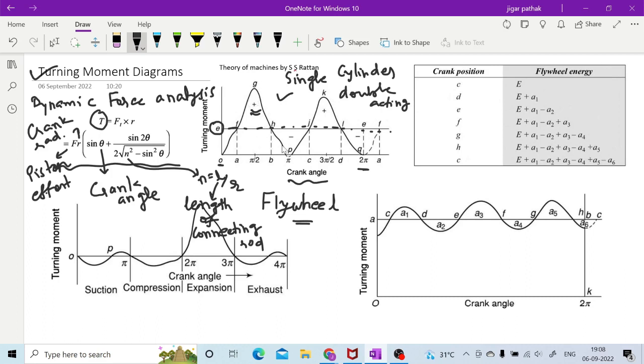And whenever the energy generation is less, here it is only this much, but the required is this also, which is mentioned in negative, this is also required, right. So when you have a flywheel in your mechanism, the flywheel is going to provide this required energy during this particular motion, while here it will store this energy because it is in excess, right. So this is how your flywheel is going to work.